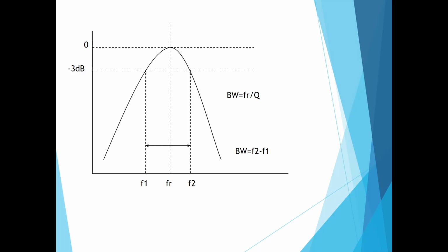Okay, this is the frequency transfer function of the filter within the tune circuit. This is the frequency response curve of the filter in the tune circuit. This is the general frequency response curve, which is a bell shape like this. Above here is 0 dB, and then minus 3 dB is here. So minus 3 dB is this dotted line.